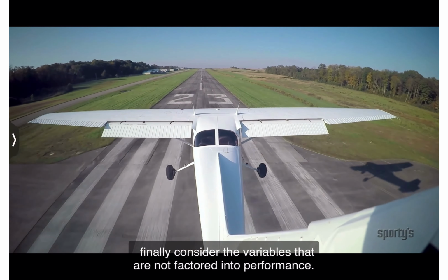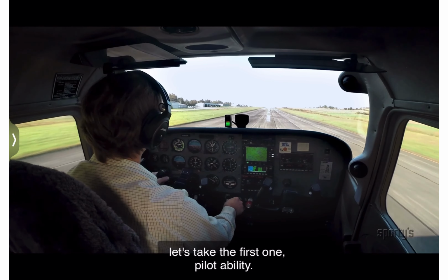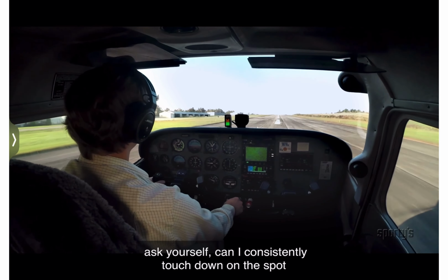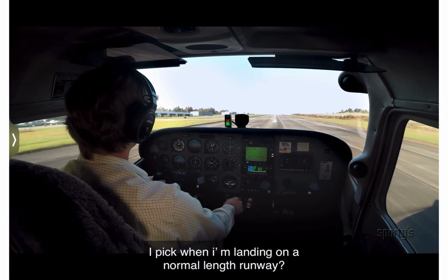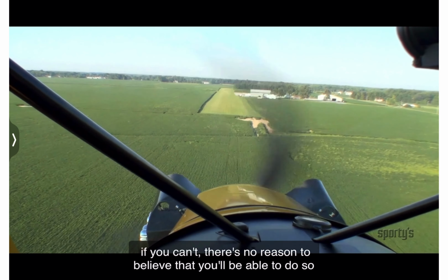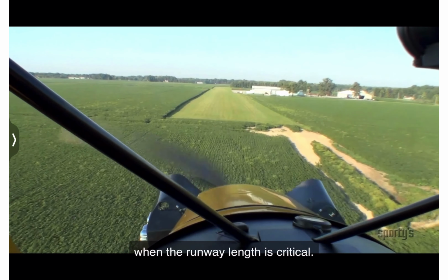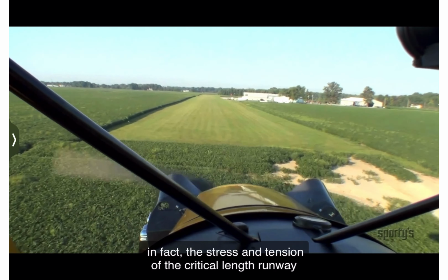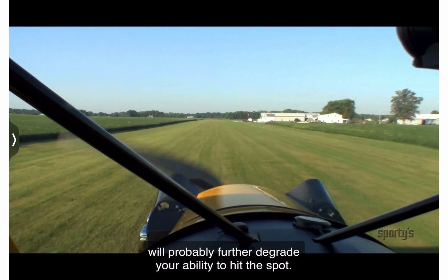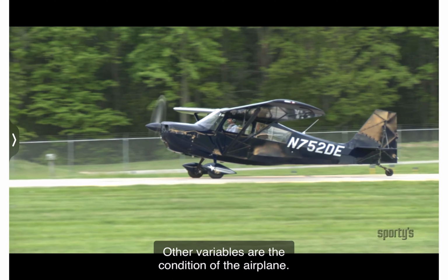Finally, consider the variables that are not factored into performance. Let's take the first one, pilot ability. Ask yourself, can I consistently touch down on the spot I pick when I'm landing on a normal length runway? If you can't, there's no reason to believe that you'll be able to do so when the runway length is critical. In fact, the stress and tension of the critical length runway will probably further degrade your ability to hit the spot.